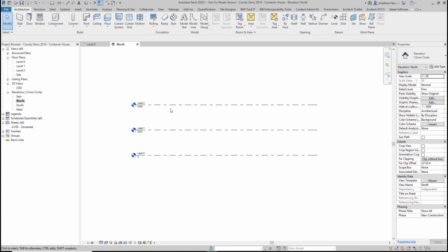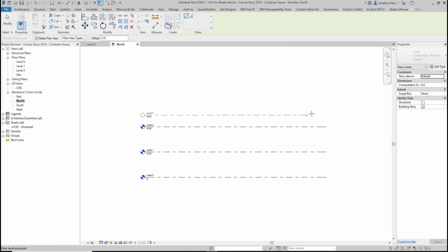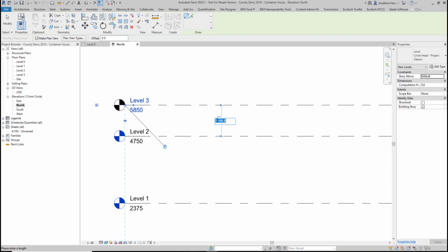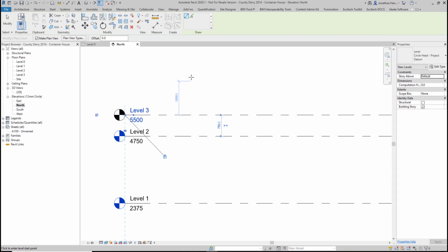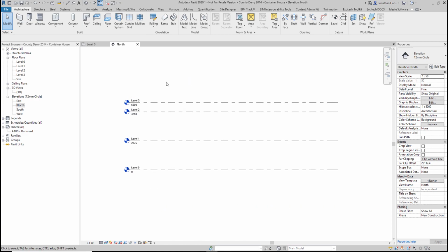This is where the first floor is, and then from the Grand Designs house there's a little chimney section, so again I'm just going to put in another level above that, tracking them across. I'm going to make that 750, hit enter, and that will adjust. So 0 to level 3.